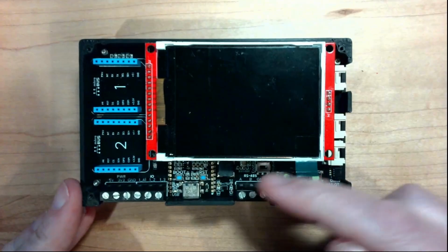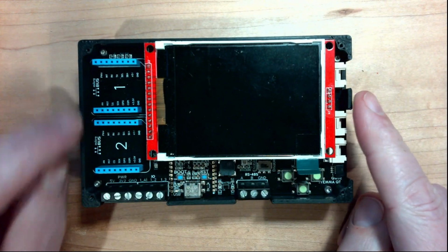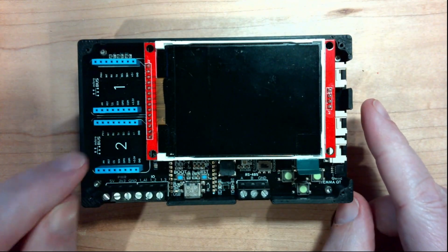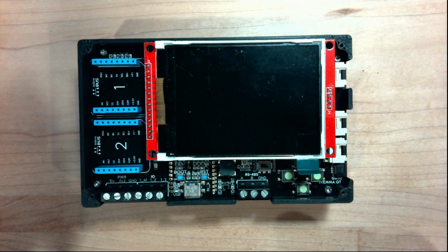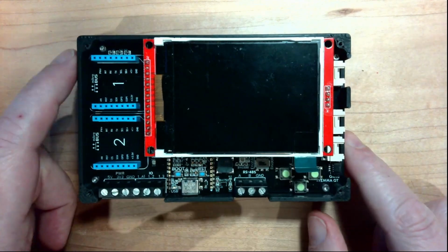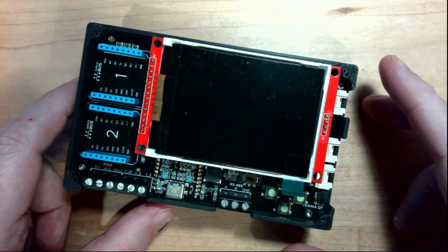And so for this one, we're going to use this hardware. This is the Wilderness Labs Project Lab. The important piece there is we have some inputs on this that it uses hardware counting instead of software counting. It's much, much faster. On this one, I could count up to at least 100,000 samples a second. We don't need anywhere near that range, but even 100 samples per second can, if you're using software, tend to saturate the processor and use up a lot of your processor time. So in this case, we're going to use this. That way we're using a hardware input for that signal. So let's wire this up and then do some code.